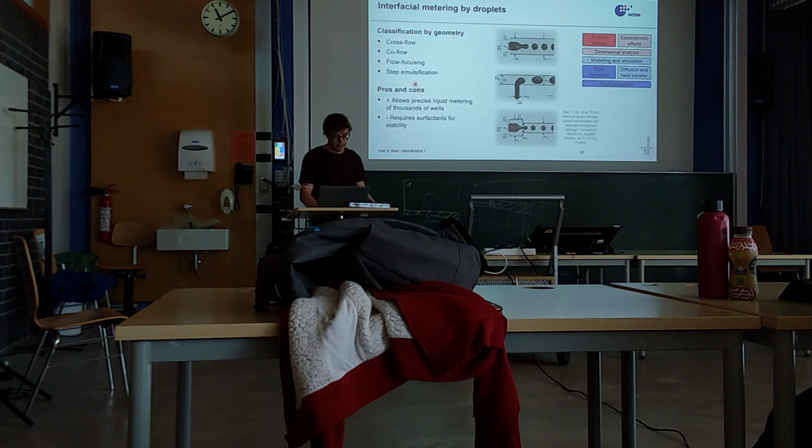So this negative point is maybe more a reminder to the surface effects lecture. If you remember, the stability of the droplets, or the soap bubble that we discussed, also depends on the surfactants. And this is the hard part about droplet microfluidics. You have to find good combinations of oil and water and surfactant, which is added to the oil, to get stable droplets and to keep them stable.